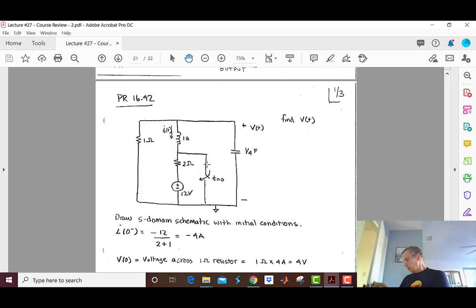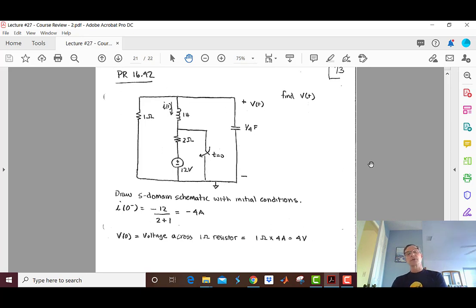And so let's just look at this thing at t equals infinity the chapter 8 way. The voltage here is going to be 0, right? Because this is shorted. At steady state, or time equals infinity, there's no voltage across the inductor, so if this is 0, that's 0. Quick enough. Asymptotic analysis got you the answer. So you could do it that way too.